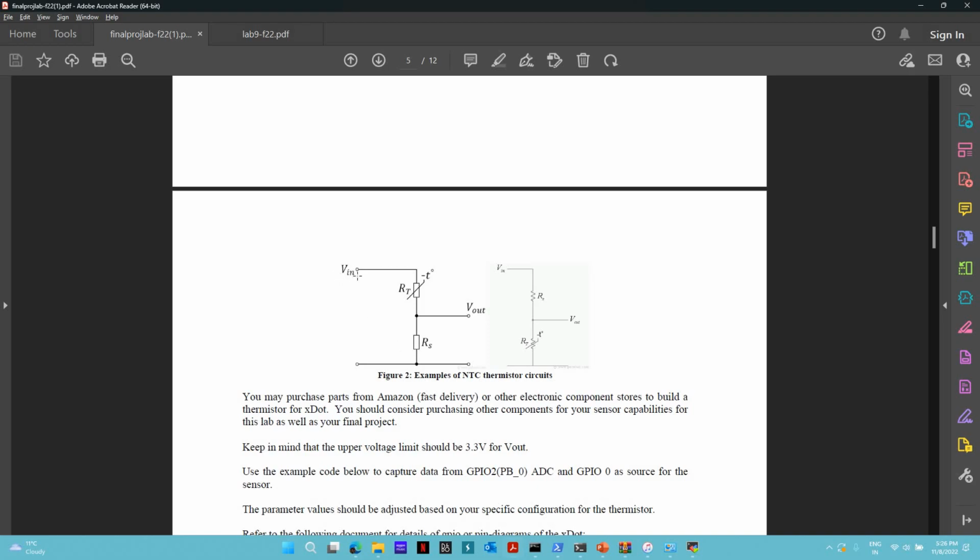So we feed the voltage input. This is going to be 3.3 volts, and then we're going to connect the thermistor, and then we're going to connect a 10 kilo ohm known resistance. We have a known resistance because we'll know the voltage drop across this resistor, and then we have the ground. So what's happening here? Input we're feeding 3.3 volts, and obviously the voltage drop should match the 3.3 volt drop according to Kirchhoff's law.